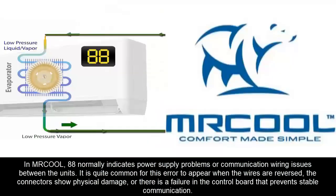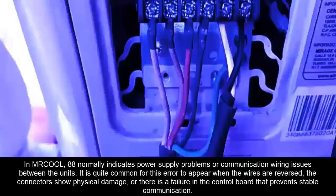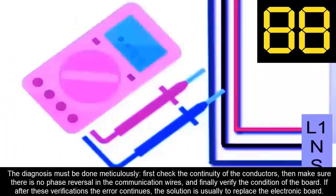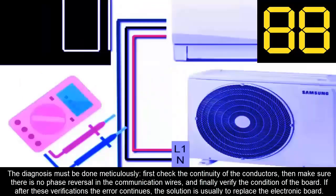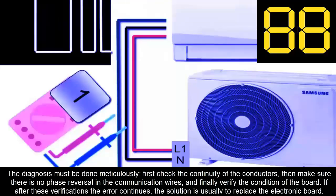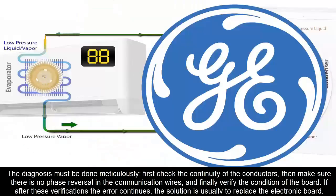In MrCool, 88 normally indicates power supply problems or communication wiring issues between the units. It is quite common for this error to appear when the wires are reversed, the connectors show physical damage, or there is a failure in the control board that prevents stable communication. The diagnosis must be done meticulously. First, check the continuity of the conductors. Then, make sure there is no phase reversal in the communication wires, and finally, verify the condition of the board. If, after these verifications, the error continues, the solution is usually to replace the electronic board.